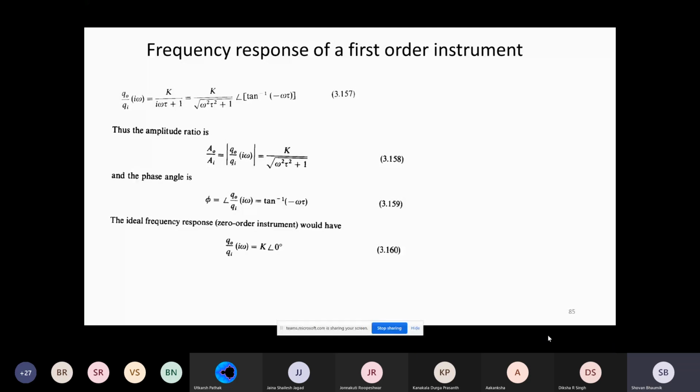But then what is very much important? Important is the amplitude ratio, the ratio of the output by input amplitude. That will be very important. So if the ratio is so important and the phase angle is so important, then rather than plotting the output, it is useful to plot frequency versus input-output amplitude ratio and frequency versus phase angle.